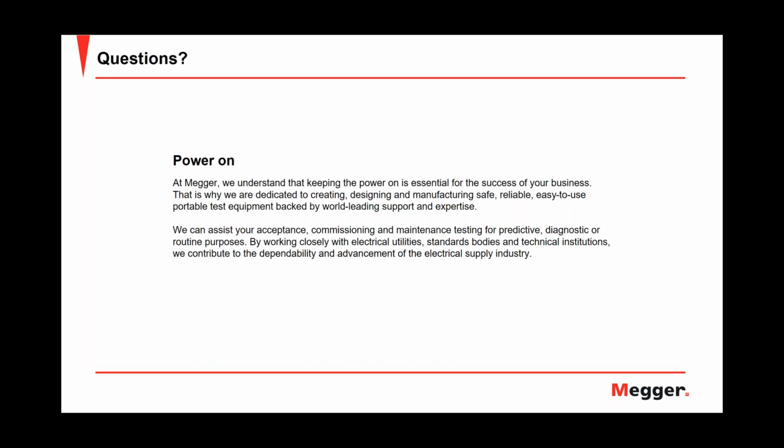Thank you. So, Robert, could you please kindly explain the physical phenomenon of the bang sound appearing when certain level voltage tests are applied on faulted cables? Okay, so what is asked here is pretty much, why do you have the sound when you apply voltage to a faulted cable? It's pretty much the phenomenon of dielectric breakdown, like the flashover that you want to achieve, and what Javier explained very well, that you need that flashover to make the method work.